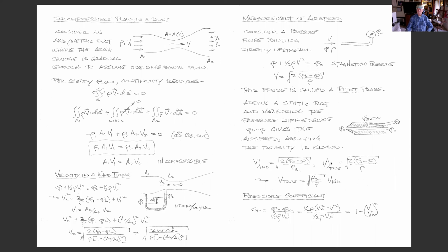But for an airplane, we talked about the aerodynamic coefficients. CL is equal to weight over wing area divided by Q infinity, dynamic pressure. And that's what gives you your lift and your drag. So it'd be nice to fly at constant Q, constant dynamic pressure. Well, that's just constant P0 minus P. Flying at constant P0 minus P, your true airspeed is higher.